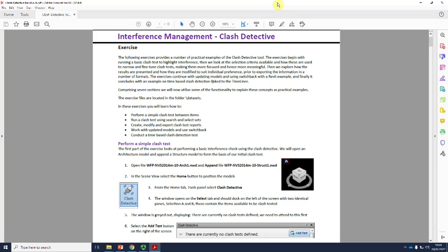Yes, let me show you a trick. Sometimes windows can be problematic. If you're working with clash detection, you have windows in here, so you will need that. To avoid opening windows over and over again when you close a file, you can save that and name it as clash detection, because for clash detection you only need this window.